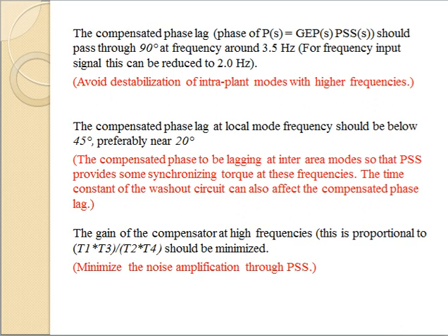So what is the reason behind that? The same which I was discussing earlier. The compensated phase should be lagging at inter area modes, so that the PSS provides some synchronizing torque at these frequencies. So in inter area modes, you are required to provide some synchronizing torque with the help of this damping torque. So this is the requirement.